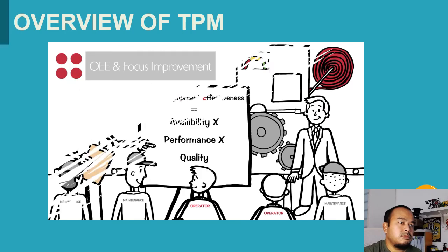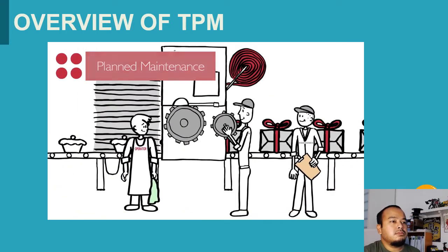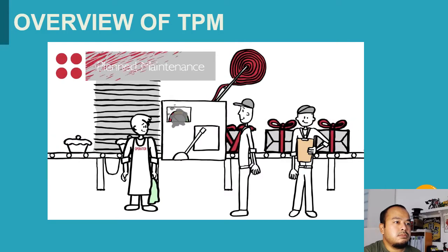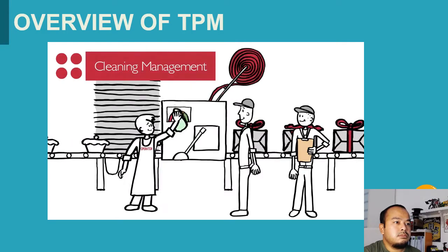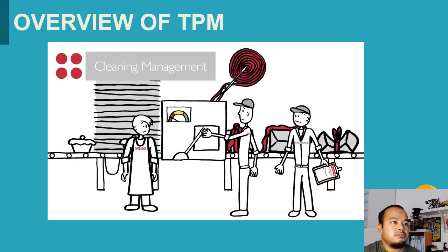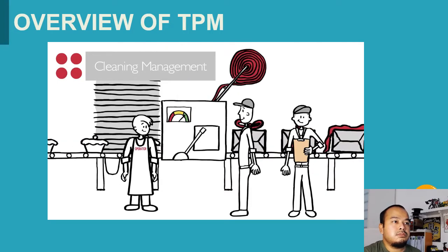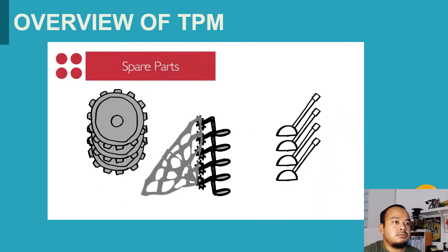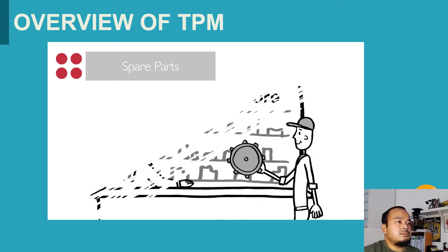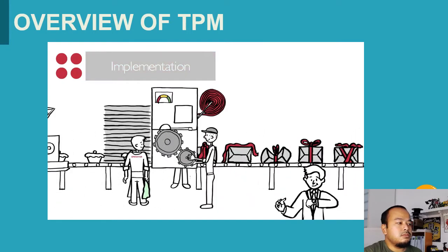We then begin planned maintenance, where routine maintenance is scheduled with actions, maintaining each part of the machine at recommended intervals to improve machine performance. Keeping the equipment clean is part of the procedure. Each team member is responsible for a clean, safe work environment. Regular cleaning can detect faults at an early stage, avoiding sudden breakdowns or bigger problems in the future. Spare parts are analyzed based on consumption and past purchases, so the spare parts that wear out often are always accessible. And once the system is set up, we take a pit stop approach to trial standard operating procedure tasks.